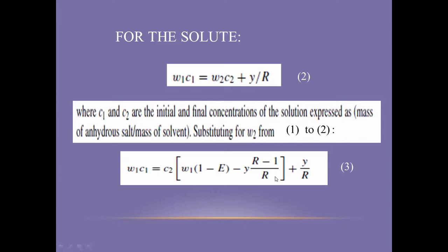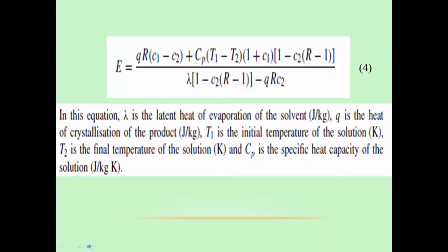The E and the R can be determined right away. So you will have just the C sub 2 as the unknown to give you the yield, if you're going to use this particular equation number 3 to determine the yield, because this E and R are simply ratios. So there's no worry about that. If there's no water evaporated, if there's no degree of evaporation, automatically this E is out of the picture. That leaves you only with the R. Okay? But there are problems, class. That is why I use caution, wherein you are to merge what you have learned in evaporation and now with this.